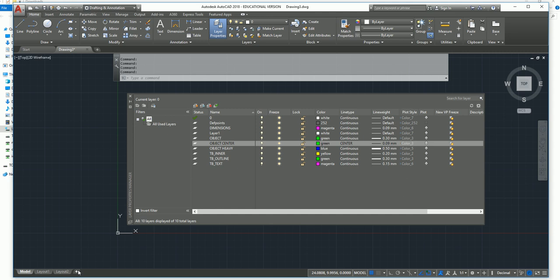Like I said, if you have a floor plan, you don't want to show your carpet squares on there, so you could turn that layer off. That's what I'm saying. Layers are really important to show each individual item. I always like to think of it as a material property equals a layer. So a wall has different material properties than the floor, than the ceiling, than this desk. You could always try to think of it that way.